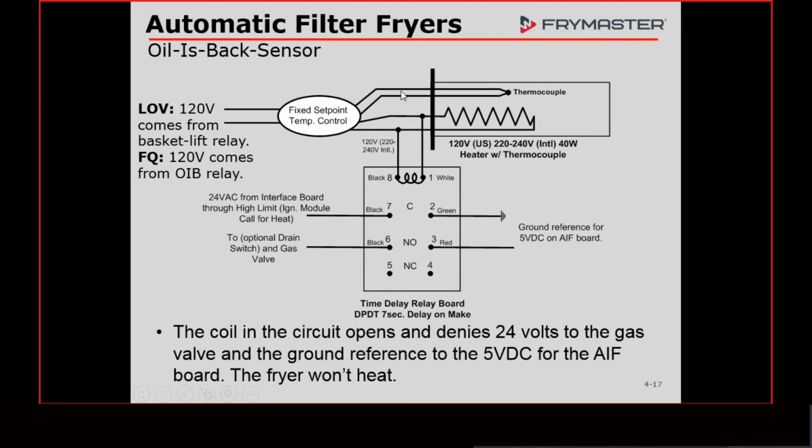Once this sends a signal back to the egg with the controls and the little circuit board in there, it knows that it's at 550 degrees. Well, guess what? We're at 550, that's set temp. We're going to shut the heater off, which means we're going to cut the 120 volts to this heater. Just like anything you set a temperature on. So it's just a heater that's set at one set temperature, 550.